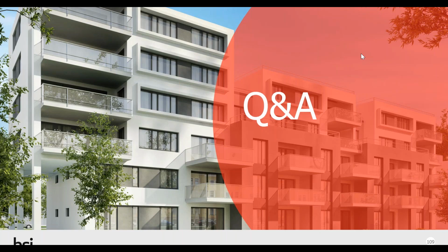And what guidance is given regarding the materials used for the balcony floor and wall finishes, including pedestal systems for flooring? In terms of the materials for the floor, they should be A1 or A2-s1,d0. It does mention that minor components can be exempt if you carry out a risk assessment that can determine that adequate resistance of fire spread can be achieved with those less performing components.